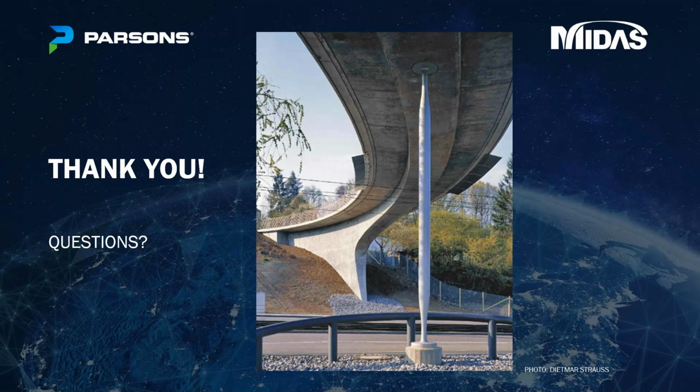But you can build a transition span to the abutments so that you redistribute the deformations continually into the soil. That requires some special techniques in terms of pavement and so on. They have done this in Austria for a bridge, but this field isn't well developed yet. You can do this for longer bridges as well, but it requires interdisciplinary review from a geotechnical and a pavement engineer. I'm not so familiar with reinforced pavement, but this is maybe a way of redistributing those kinds of deformations.